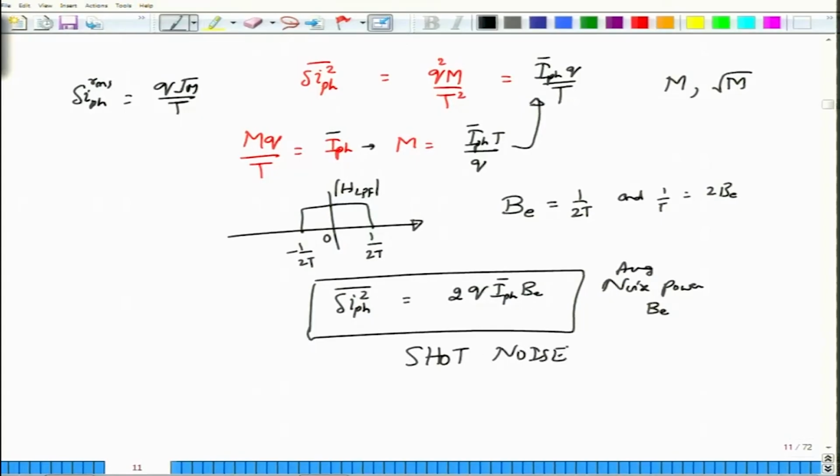And please note that in this derivation of the shot noise expression, what we have said is all about the source uncertainty. We have not actually considered the shot noise of the device, but the device is assumed to be ideal. Whenever there is a photon pulse, it will generate a current pulse, and therefore it is actually the source, which is our laser source, that exhibits uncertainties. So whatever shot noise results from the photodetector, even an ideal photodetector, is simply because of the laser or light source itself.